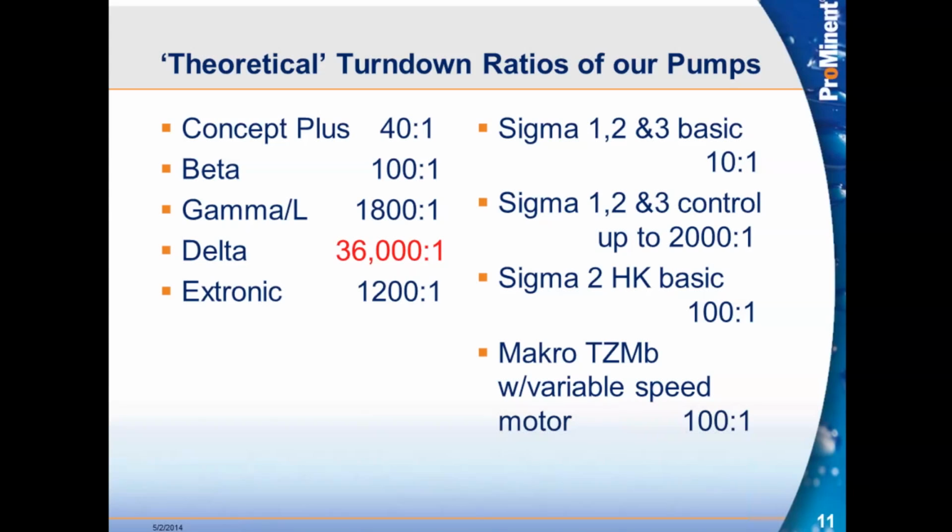So you have to look at both of those products, both the VFD or the SCR drive for a DC motor, as well as the motor itself, whether it's the DC or the inverter duty motor. Whichever one is the lowest turn down, that's the one that you have to use on your calculation for the overall turn down.